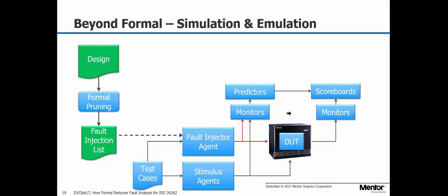Even if you don't start with formal and you are using only simulation or emulation, the formal utilities that optimize the fault list are necessary, because they give you an optimized fault list, and then you don't have to spend a lot of work injecting faults that do not have an impact on your results.